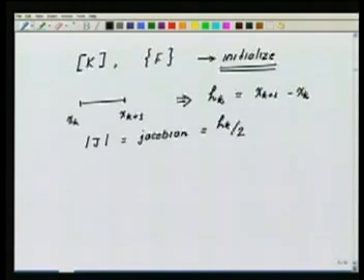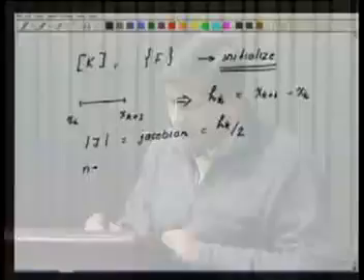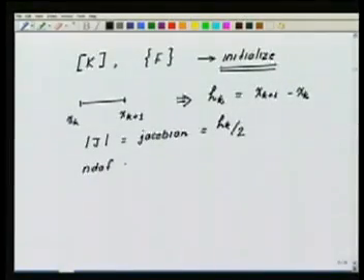Okay. So, I am following the steps in the way you have to do things in a computer program. Then what else do I do? So, given P, I will define the number of degrees of freedom in the element is equal to P plus 1, and I give it a name, endof. What else do I need to do? So, given this endof, given the size of the element, given the J, now I start a loop over the integration points.